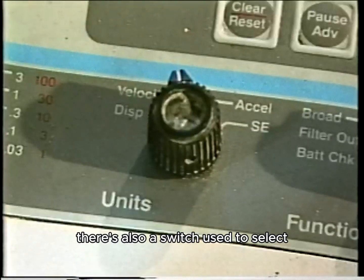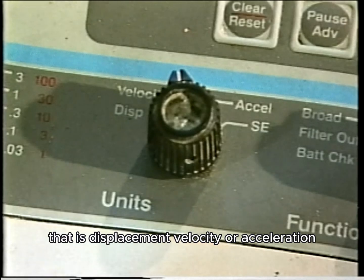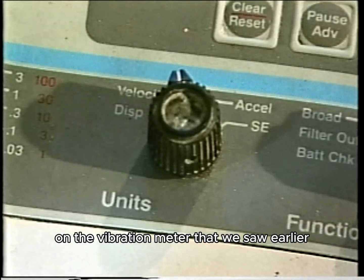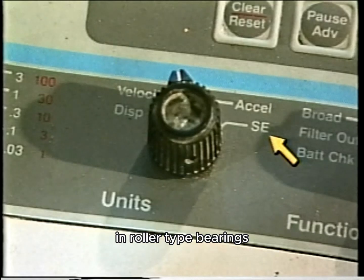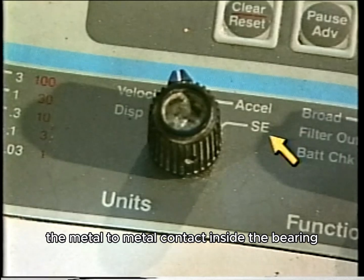There's also a switch used to select the parameter to be monitored, that is, displacement, velocity, or acceleration. Like the parameter selection switch on the vibration meter that we saw earlier, this switch also has a setting used to detect faults in roller-type bearings. If the switch is set to this position, the analyzer will monitor the metal-to-metal contact inside the bearing.